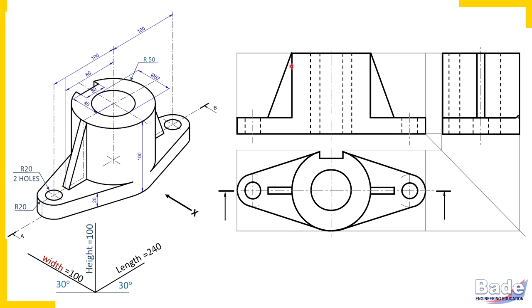And then if the largest surface of a plate appears in the sectional view, then the plates are assumed uncut. So this triangular plate, and also on this side the triangular plate, we should assume uncut.